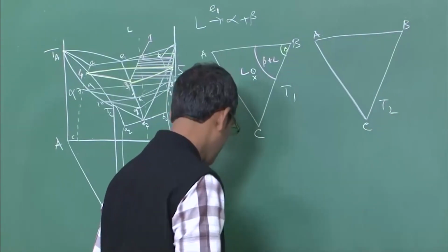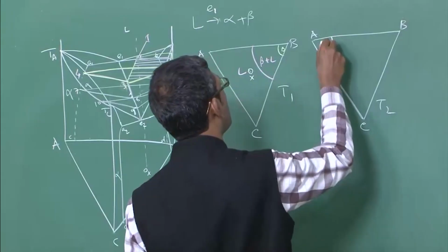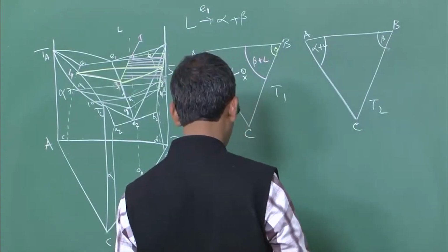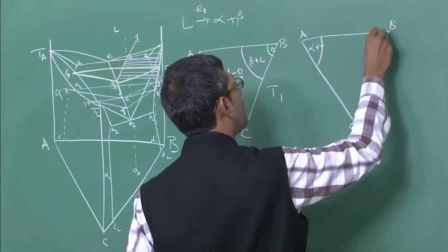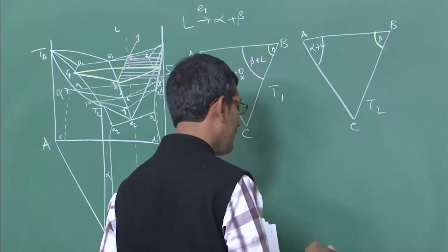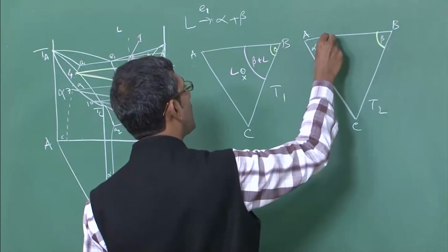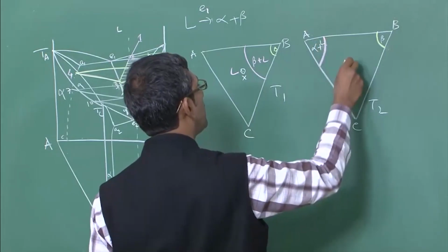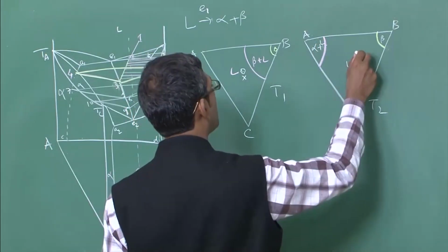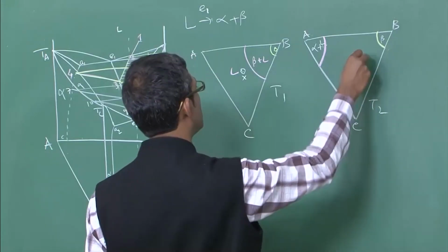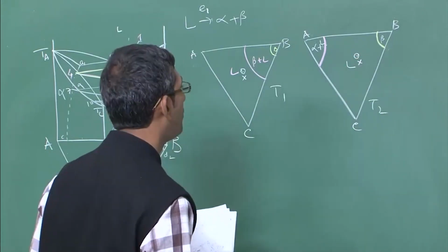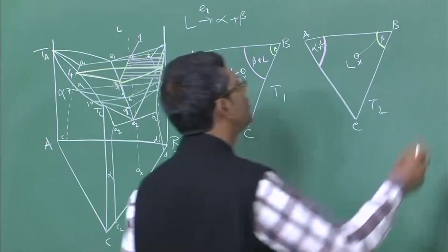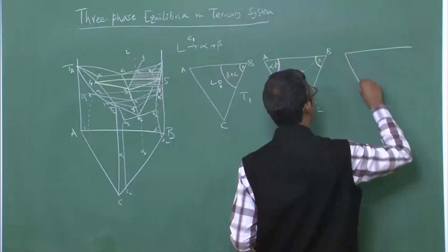At T2 the diagram will slightly change, you are going to have alpha plus liquid, beta, okay, let me draw it this way, in color, then it is easier for you to follow. So, this is beta, all green things will be solid for me, and any solid plus liquid region or liquid will be like this. So, this is alpha plus liquid, this is liquid. Again my alloy composition X is sitting somewhere there. It will just form a little bit of beta, as you can see here, you can draw a line, it will form beta. But things will be much clearer once you look at this one at T3.